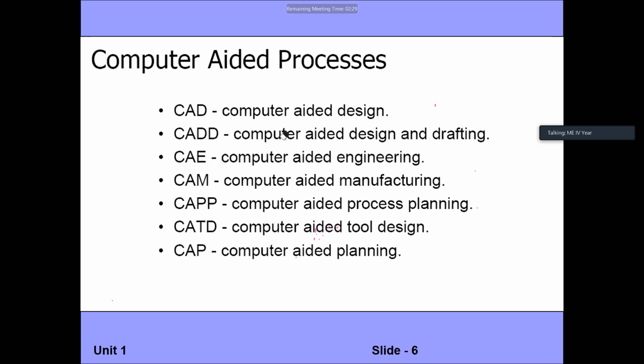Am I right? That is the input. Once the input is there, you model it, create all the 3D models of the parts, and assemble them. Then in an actual company, after completion of the modeling and assembly, they will convert the same model according to the customer requirement. That means front view, top view, assembly front view, assembly top view, and assembly sectional view. All these things will be covered in the drafting.